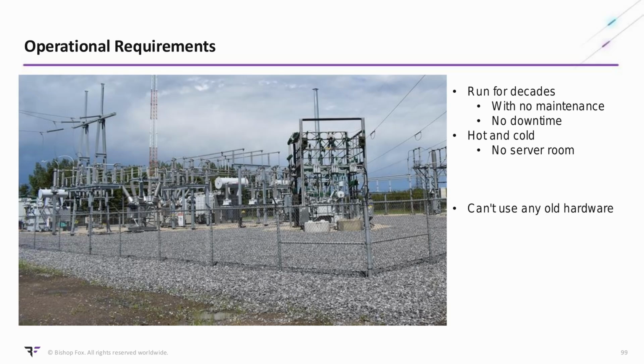Also, that means that any particular piece of hardware that you see out in the wild might be really, really old. For some of the audience members, there might very well be RTUs in operation that are older than you, which is just wild. One conclusion you might draw from that is that some of that hardware is just physically incapable of doing encryption. It just doesn't have the necessary CPU cycles to encrypt the connections. It's just too old, it's too slow to do that.